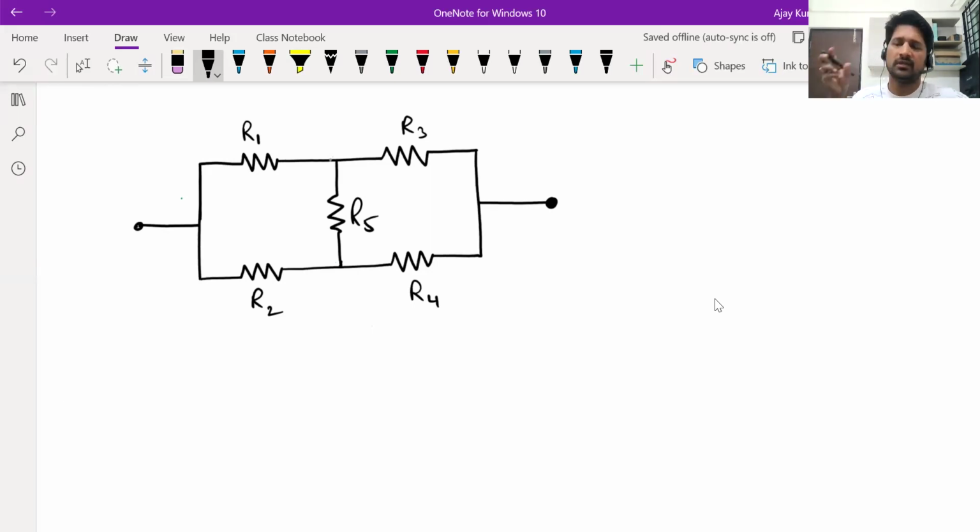We have to find out the effective resistance of this network, no? So what we'll do is we'll assume a battery is connected. We'll find out how much current flows through it because of that battery. Then we will divide them. We know V is equal to IR, so R should be V divided by I. So we'll assume there is a V connected. We'll find out how much current I flows. We'll divide them, we'll get R.